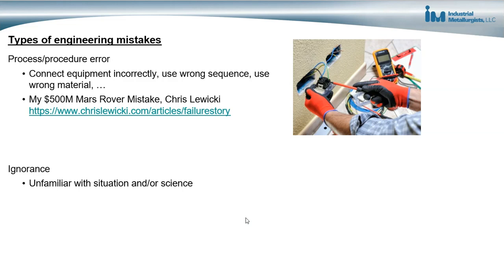And it turns out that the change I made resulted in a layer of aluminum, an extremely thin layer, like nanometers thick, being deposited onto the wafers. And because I removed the subsequent cleaning step, that layer was not cleaned off. So as a result of having that very thin layer of aluminum on the wafer, that layer of aluminum interfered with a process that was going to occur next after the cleaning process that affected the electrical behavior of the integrated circuits, and basically it ruined the wafers. So all the product had to be scrapped. So that was an example where I tried to use intuition without a good understanding of what was going on with the chemicals and the effects of the cleaning processes. And I'll explain more about that.